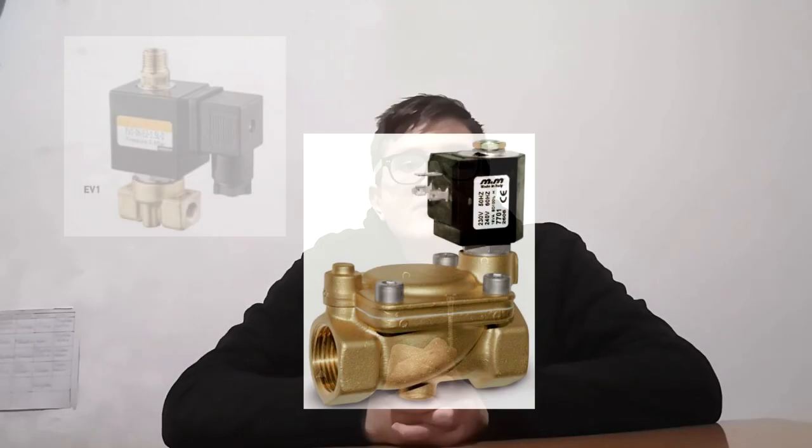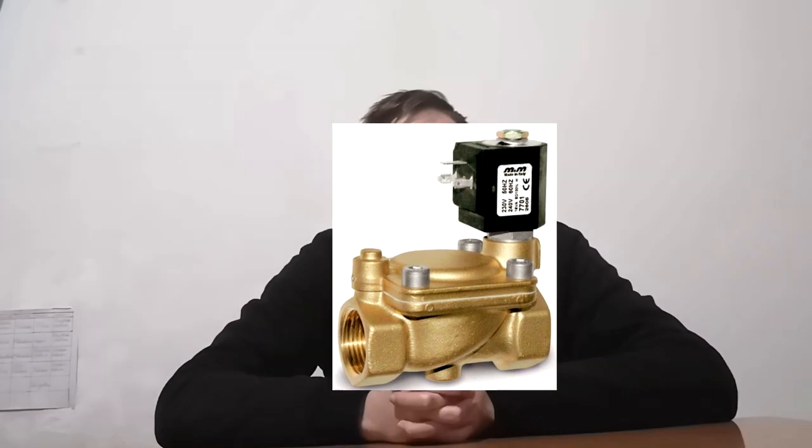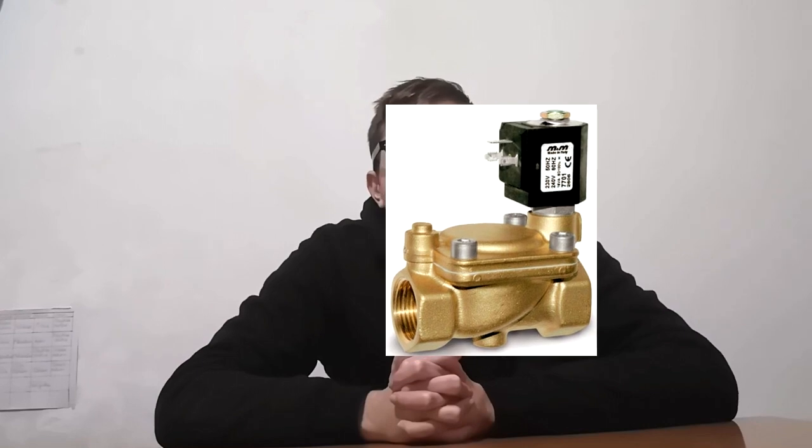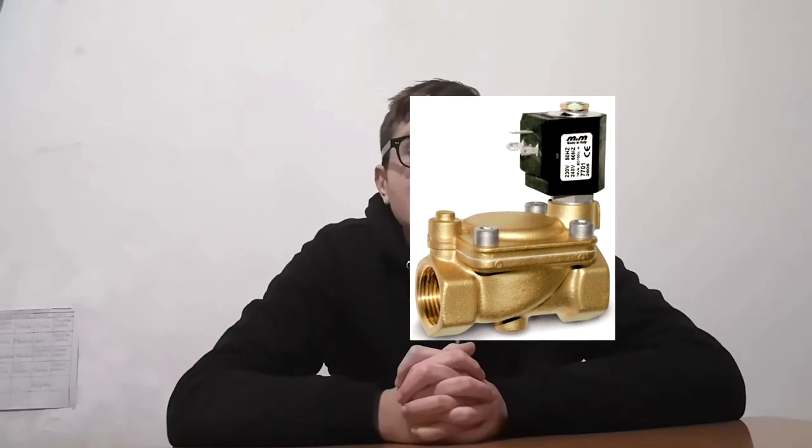The servo-controlled solenoid valve has a pilot orifice and a main orifice. The magnet will open and close only the pilot, so the maximum and the minimum operating pressure will not depend on the power of the electromagnet, but on the construction characteristics of the seal on the main orifice. A fundamental characteristic for this type of solenoid valve is the minimum operating pressure, which is always greater than 0. All solenoid valves are divided in normally closed and normally open.